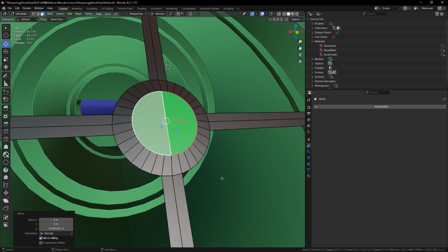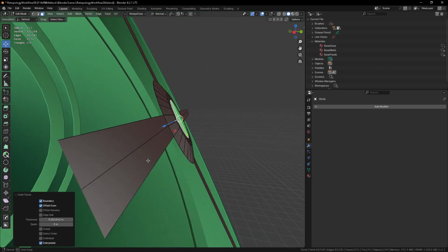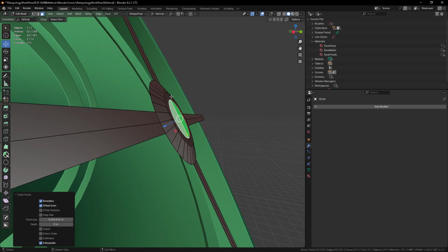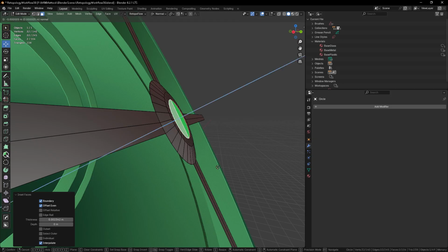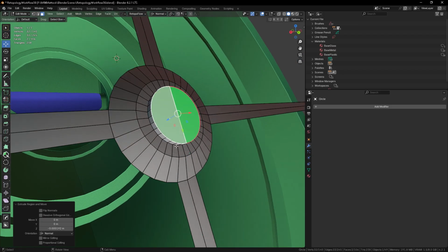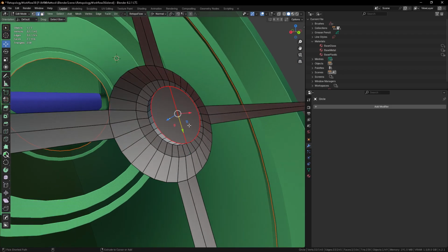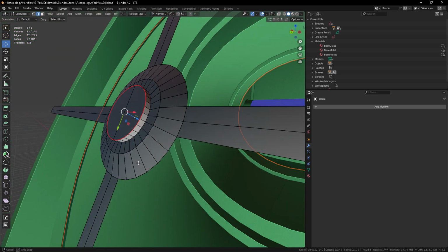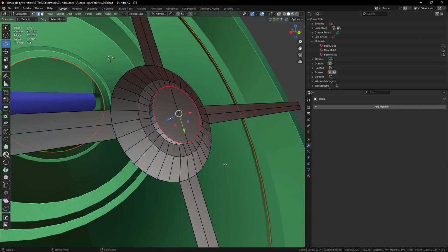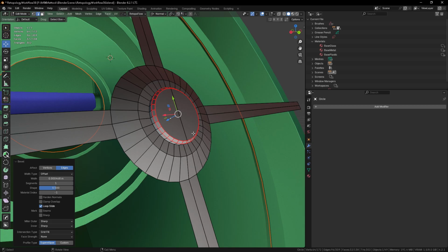Let's press I again and set the new polygon strips all around, and extrude and pull it up just like this. And okay, let's switch to edge mode and deselect this loop in the middle and press B, and let's give it a nice chamfer just like that.